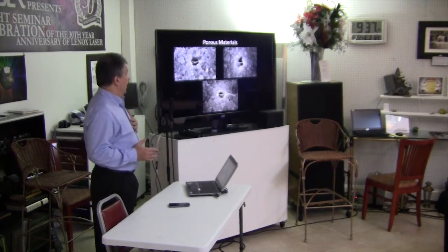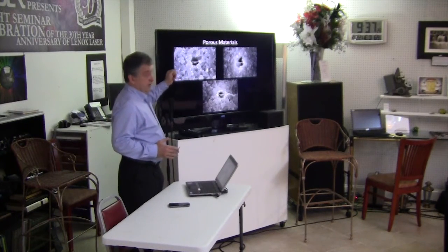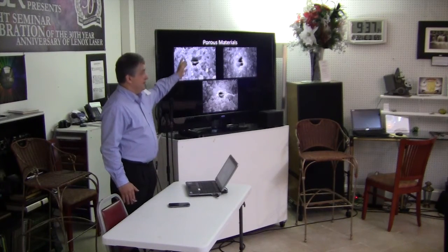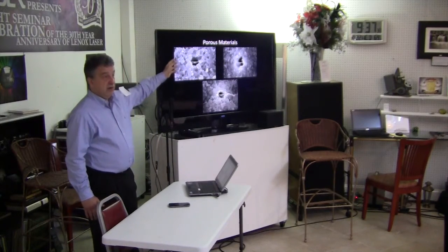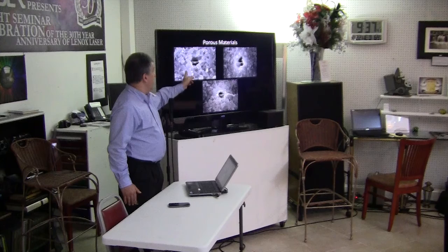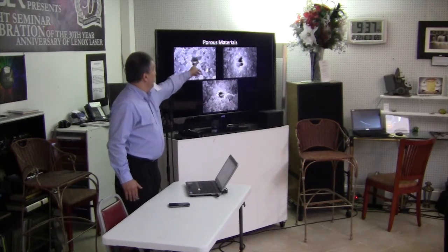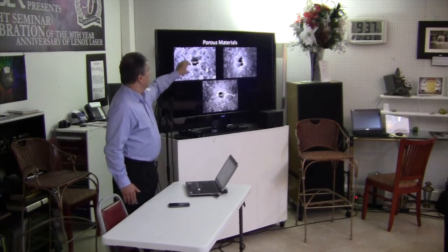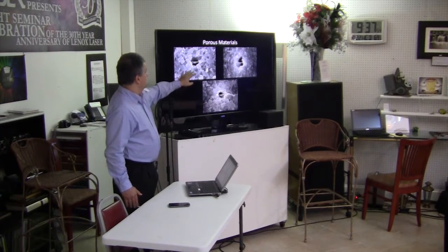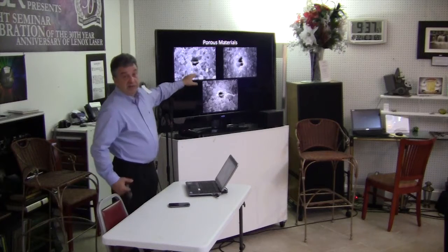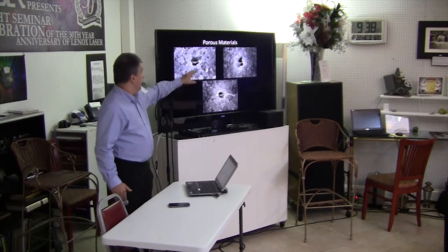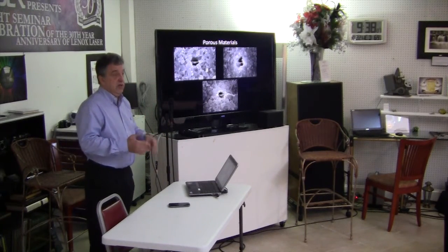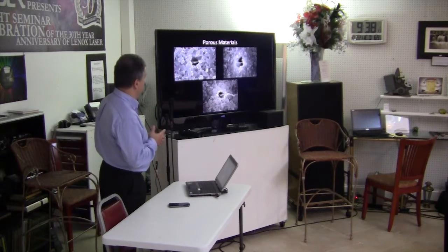So the question becomes, okay, we can drill in this material, but how do we calibrate it? Because it's spec'd with an open area. In other words, it has, let's say, half a micron or micron holes already built in by the methods in this material. And if we drill one, how do we measure? So we limit the area. We blow the gas through the area with no hole in it. We find out what's the leakage of that particular area. Then we drill the hole there, and using the same area compare by the deviation. Okay, the leak shall increase by so much.